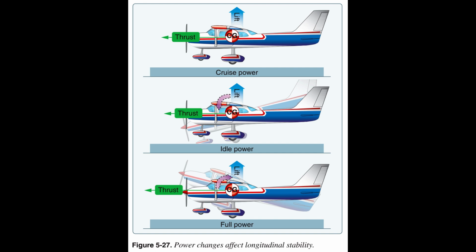The following is a simple demonstration of longitudinal stability. Trim the aircraft for hands-off control in level flight. Then, momentarily give the controls a slight push to nose the aircraft down. If, within a brief period, the nose rises towards the original position, the aircraft is statically stable.